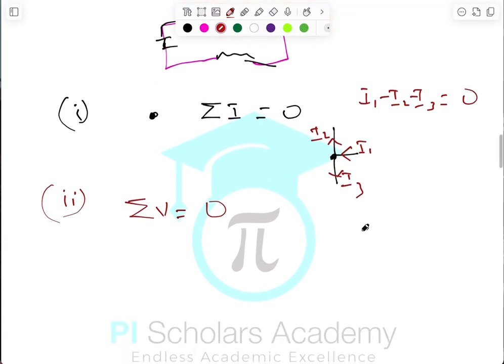It depends on how you are moving in your path. For cells, when you draw any straight arrow directly in between the positive and the negative terminal, if you notice that your movement is going from negative to positive, in that situation, the value of the EMF in the cell is going to be a positive value.